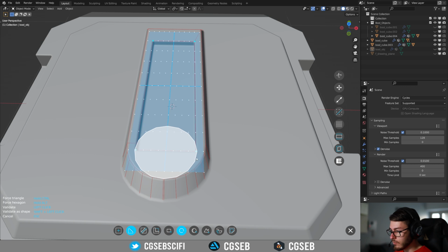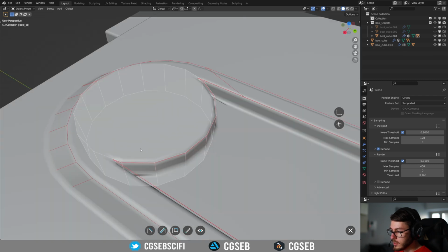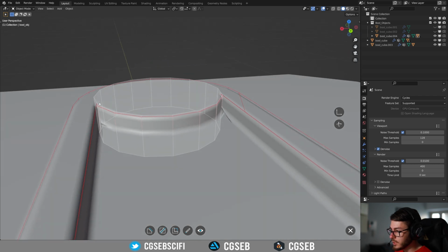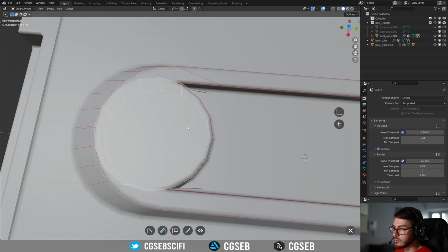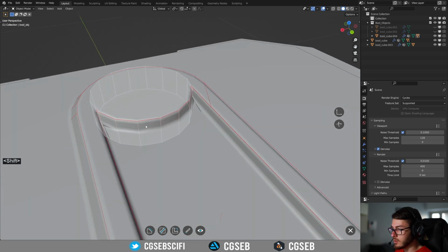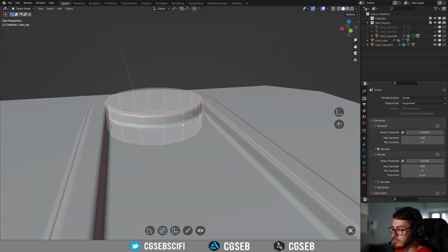As you can see, we need to go a little bit bigger than the width of here. We have a shading problem, and this is because those segments over there are pretty close to those here. To fix that, we can just play with the resolution of the circle and see if we can fix it.